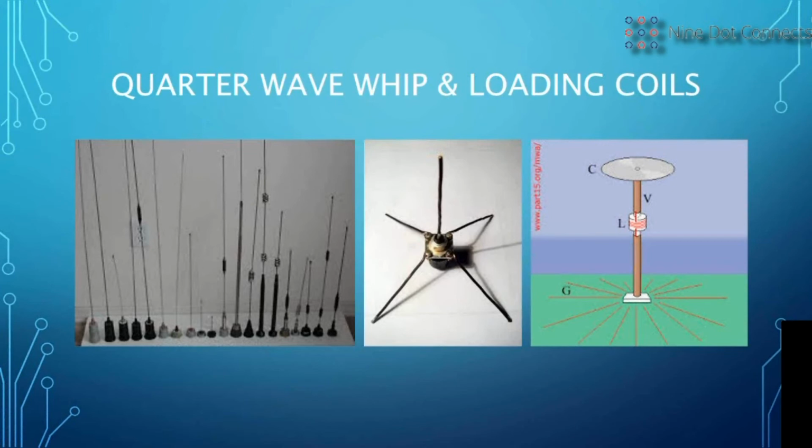So far we've talked primarily about quarter wave antennas, but there's also half-wave dipoles. Half-wave dipoles are essentially two quarter wave antennas stuck back to back. In the upper left you'll see a classic dipole, which is open on the ends and in essence shorted in the middle. And because coax tends to be a very low impedance, like 50 or 75 ohms, they normally feed these things near the center. Down in the lower left, you have one that's a complete wavelength long, but that is just folded and flattened. That's called a folded dipole.